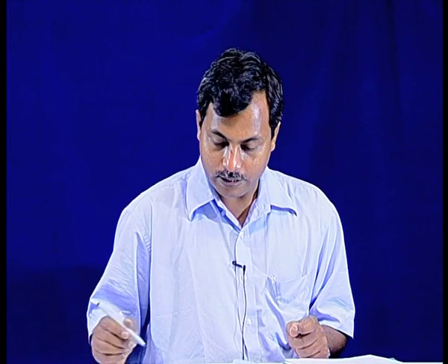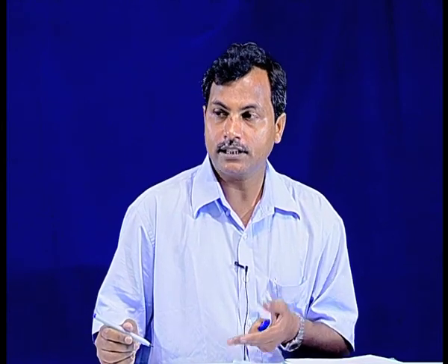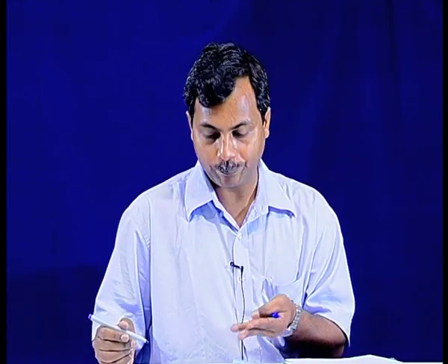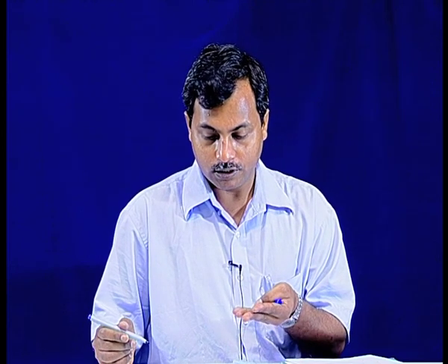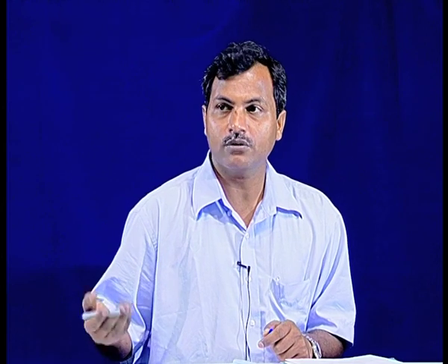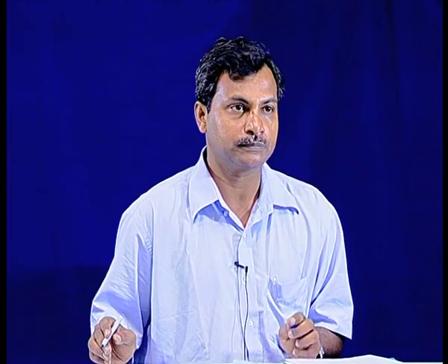Now, if you compute the heat transfer coefficient using these relations and the other one, the difference will be in the order of 10 to 12%, maximum 15 to 20%, not more than that. So, anyone can be used for a rough estimation. Okay. So, we end the free convection here. Free convection is full of correlations basically, and you have to select a proper correlation to calculate the heat transfer coefficient and ultimately the heat transfer rate. Thank you.